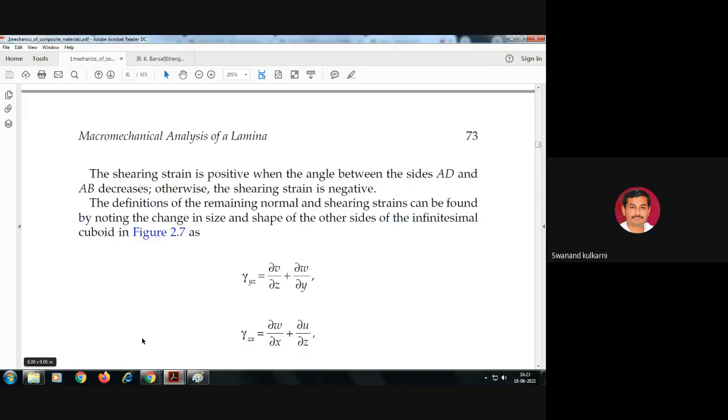0.14 mm. Very thin. For 1 centimeter there are 10 mm, and if we take 1 mm and divide it into 10 parts, then it is about 1 to 2 parts. So the thickness of the lamina is that small, and a number of such laminae are compiled together in order to form one laminate.